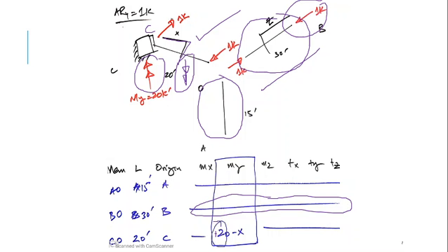Next, this one kip is in Z direction, this is X, and if you move it towards this, it is forming a clockwise moment. The load is in Z, member is in X, so moment would be in Y, so it will come under this MY. Clockwise X should be balanced with anti, so minus X.